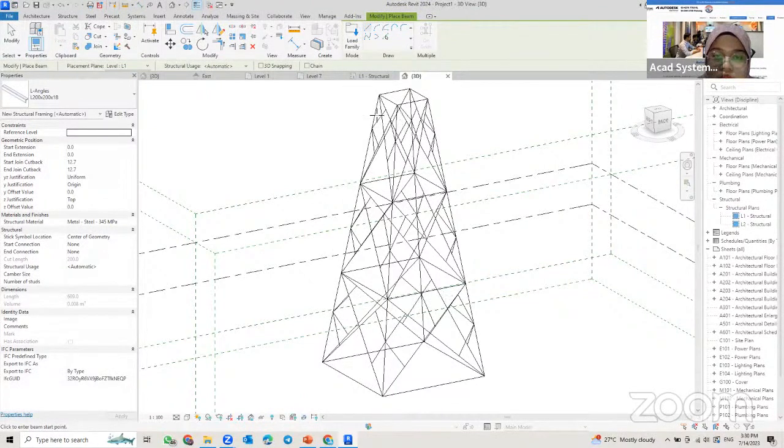To add in our massing frame, you're going to use pick line, because we already have the line. We don't have to create a new line. Just pick the existing line here.